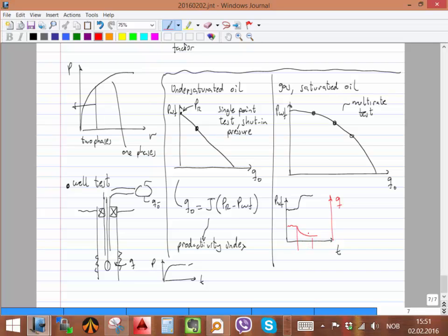This period depends on the formation. Okay, what is the velocity at which the pressure changes propagate in the formation? And sometimes this period for a well might be 1 day with very good productivity, 2 days, but some wells you have to pass months. For shale wells in the US, it has to be months to reach equilibrium. So testing each point is expensive. So we say another point, for example, another pressure going up.